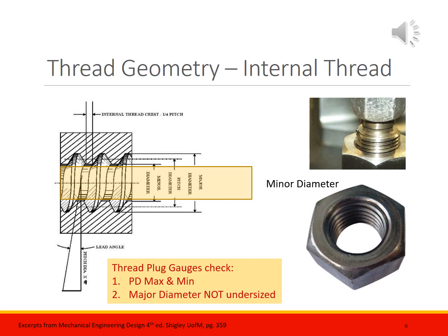So, how do you check the minor diameter of a nut? With a pin gauge. And I'll go through that example in a bit. Now, the major diameter of this internal threaded design here is the largest diameter cut by the threading operation, and it is listed on the diagram as well.